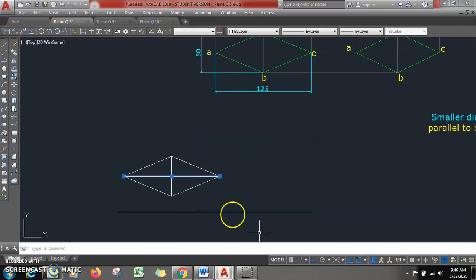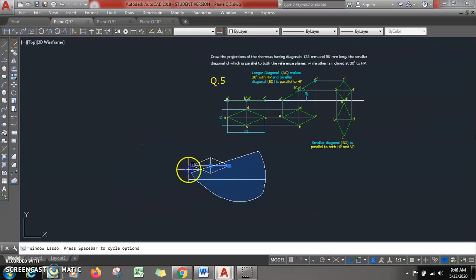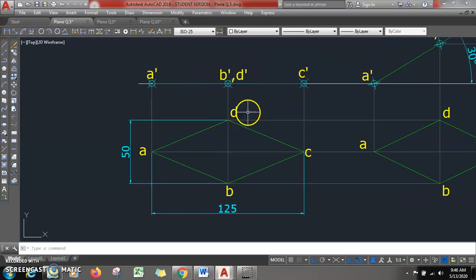If it were resting on VP, for the second step we should have phi plane. So it means that it is not resting on VP, it is resting on HP, on its corner. So how do we get it when it is resting on HP? Initially we assume that the complete plane is in HP, so the top view will be a rhombus and the front view will be a straight line.